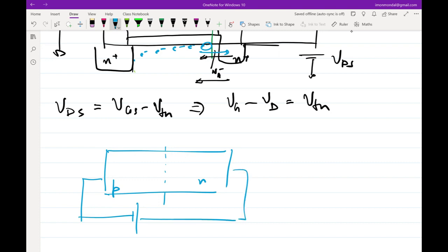In a reverse bias condition, this depletion region that we saw here, you had Na minus, here you had Nd plus. There was electric field from N to P. Okay, but let's assume that you have dropped some electrons in this depletion region. How is a matter of detail.